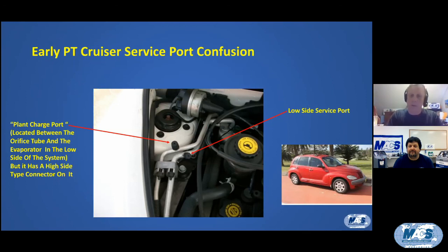They're reading the pressure on both gauges in the low side. It'll tend to be a little bit higher over here than it will be down here because of the distance that the refrigerant has to travel. But they might look at it and say, gosh, I've only got 65 pounds of high side pressure, and I've got 60 pounds of low side pressure. I've got a bad compressor because it's 90 degrees and I should have well over 200, maybe 200 pounds of pressure. So I've only got 65 pounds of pressure. So I've got a bad compressor.